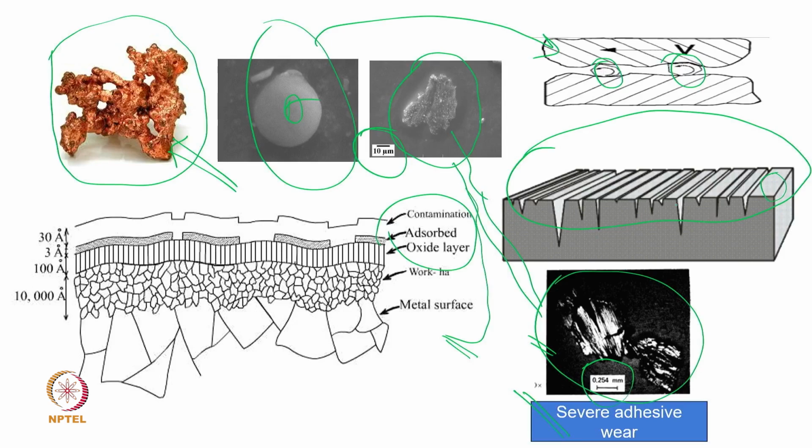In fact, it can really act as having a number of micro grooves which act like a dustbin. So, this kind of surface will be recommended for long service life compared to even the flat surface, because a flat surface will not have this kind of valleys, and naturally they cannot store this kind of particles. Those need to be immediately separated from the surface or removed from the interface, while in this case there is a scope, there is a slight discontinuity.